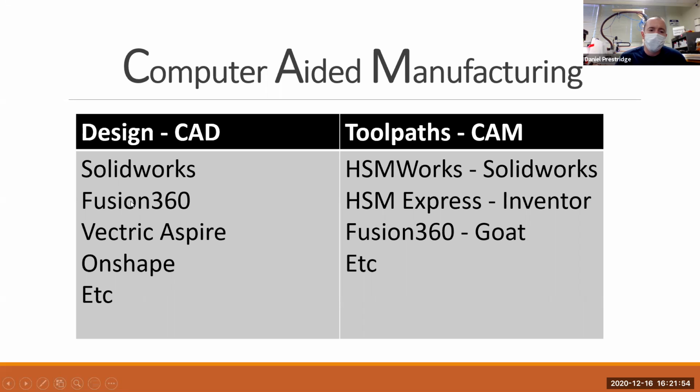And then for the design side of it, the normal things, there's a program called Vectric Aspire, and then there's lesser ones that do things, but they're really good for being super straightforward on really simple 2D cuts. If you're just doing a bunch of gussets or a bunch of belly pans or stuff like that, it minimizes the extra stuff that you'd get from Fusion 360 and the 3D tool paths. With the lower end ones you wouldn't get the ability to do the contours that you need in 3D space.